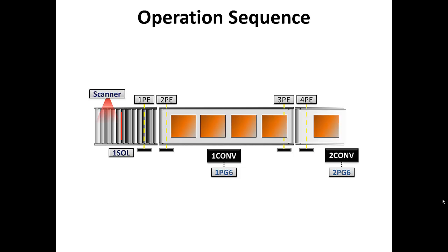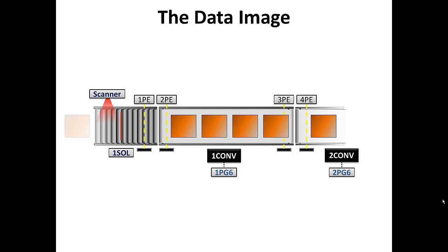So we would not turn on the first conveyor, the middle one there, the buffer conveyor, unless the takeaway conveyor, the one furthest to the right, was turned on, thereby calling for a carton. So we'll send in another one. Code's good, stop goes down, it goes down to the bottom. Now it wouldn't turn on here unless the takeaway conveyor was calling for one.